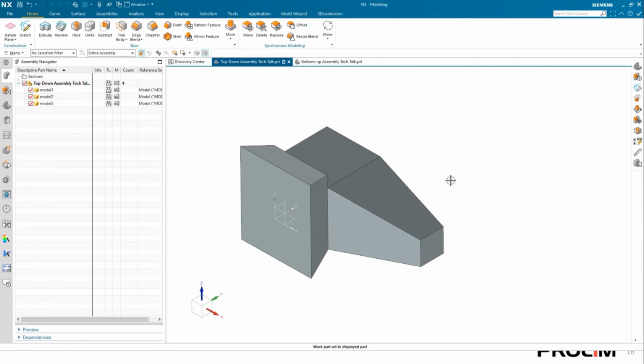And this is why the wave geometry linker is frankly more foolproof than just using sketches and these reference bodies, because essentially the sketches weren't designed to update automatically, whereas the wave geometry was made specifically to update when one thing is changed.